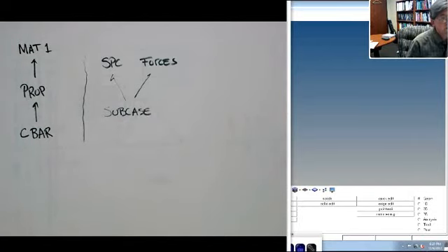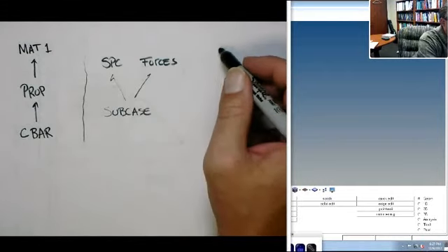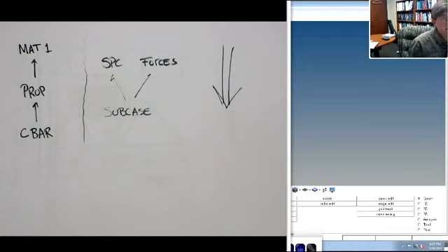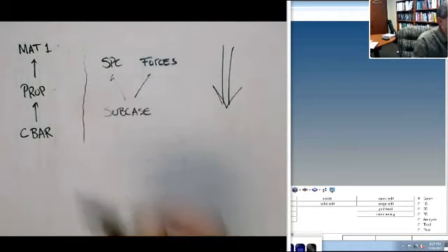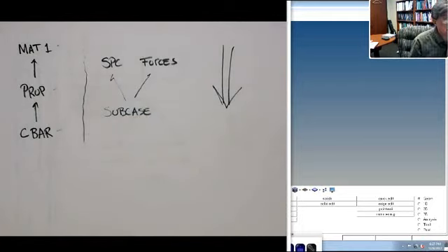In Hypermesh, you can go back and edit things, but I think things work relatively smoothly if you move down in this manner. What I mean by that is first define the materials, then define the properties, the PBAR cards or PBARL cards, then define the actual elements.